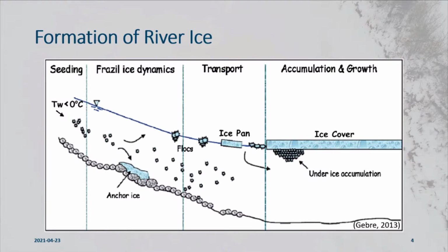And that's as opposed to something like frazil ice, which is formed in more turbulent water and begins as small, sticky, plate-like particles. So this is ice that's forming in the water column, and then as it's being worked around by turbulence, it doesn't have a chance to form these smooth sheets on the surface, but instead is formed as small particles.